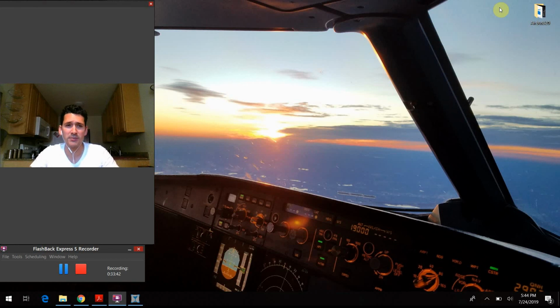So you find yourself in these situations where you either have to plan ahead because you know the airport so well, you know where the uphill sections are, so you plan your second engine start accordingly. But there are certainly times where you'll find yourself thinking, shoot, we don't have enough thrust to get up this hill, so you have to start the second engine and use 2 engines to taxi. As part of that, we never use more than 50% N1 during taxi operations, because of course we don't want to damage any aircraft behind us. And around every airport, there's all sorts of ground service vehicles and people working out there, so you never want to be putting out an excessive amount of thrust, because you could damage things, you could hurt people. So it's one of the things we operate by. As you can imagine, there are situations where you really do need 2 engines to taxi the aircraft.